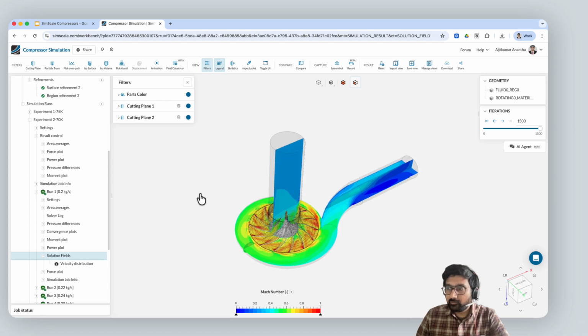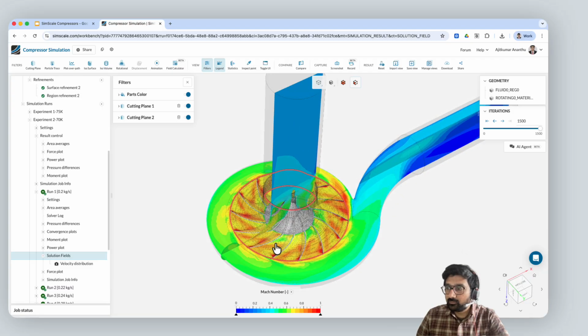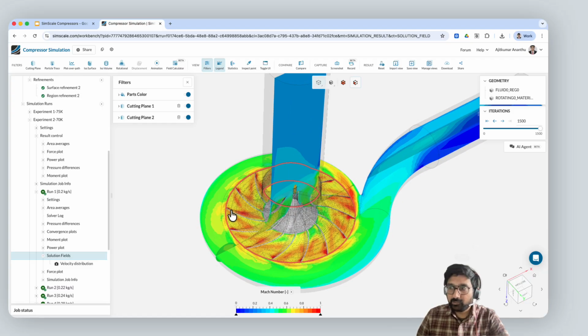You can look at the low flow rate regions where the compressor acts exactly as expected, where you'll be able to find design insights in terms of tip speeds, also see the distribution of velocity and Mach number around the blades and the diffuser region. This is a good example of a compressor working at a good efficiency range. Hence, we don't see any abnormal flow characteristics.